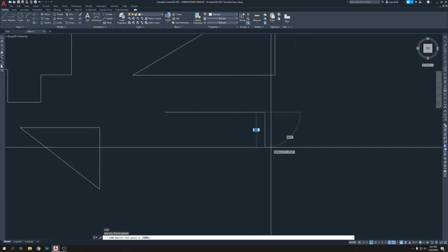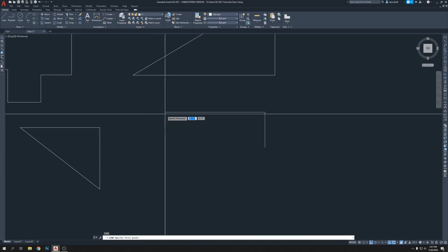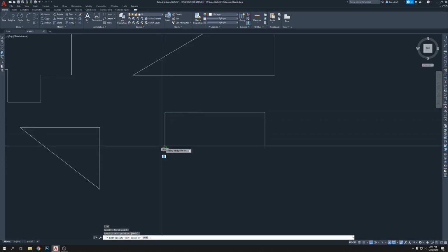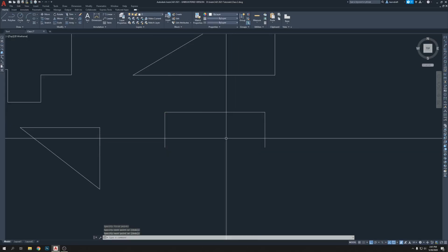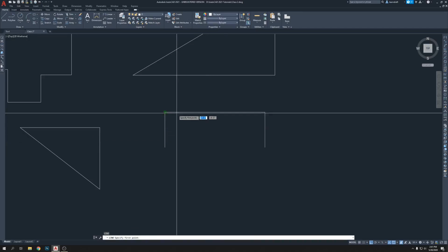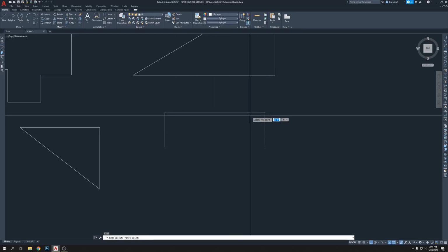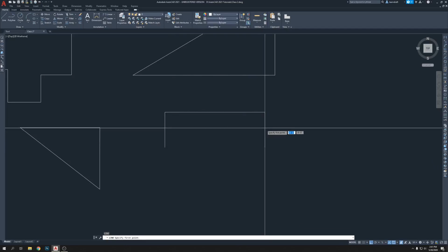So bring it here, click, enter. Then you again press L, enter, click here, bring it down, enter. Now you want to draw a line on the center, so it's going to bring out another logic behind it. So L, enter. Now we can't find the center point, because this way, the first point or last point, I mean both end points are being selected, no center point selecting, you see, no center.